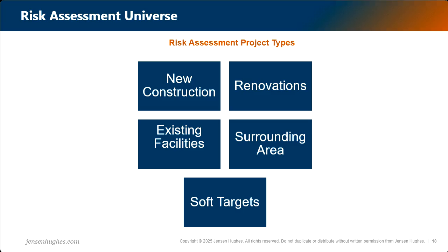How we do that is, as I mentioned earlier, our construction background. We really want to see the viable deployment of scaling up these systems, or in some cases scaling down, with cameras being legacy on a coax system. 9 out of 10 times we're seeing a conduit infrastructure that's sized for coax, which, as I think most of you know, you're able to do so much more with category cabling and potential fiber optics.